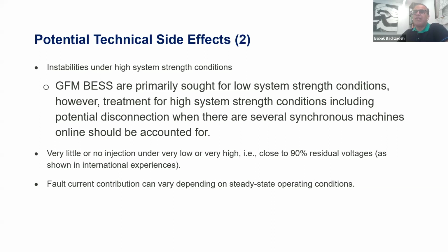So with grid following inverters, essentially they require as constant a voltage as possible. They come with very tight control of the current. So they don't have any susceptibility to current control devices, but they require good voltage control in the system, or a stiff voltage source, excuse me, not control per se, where the control comes from the stiffness.